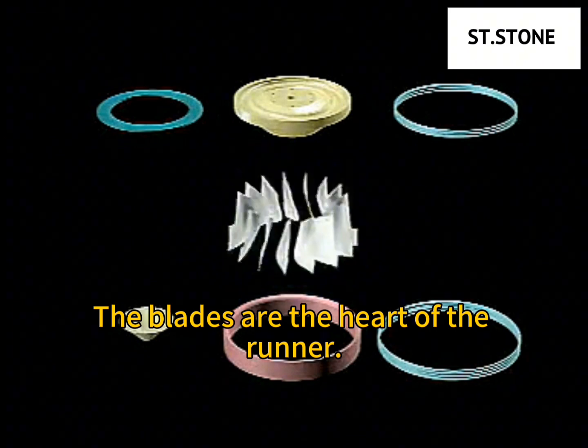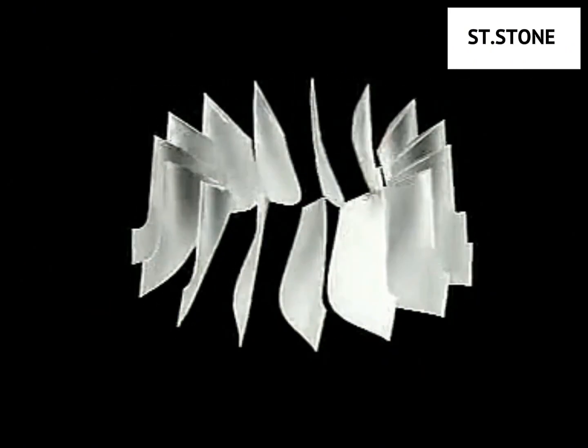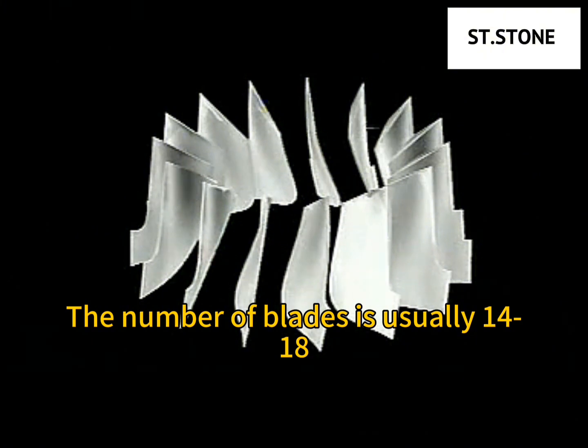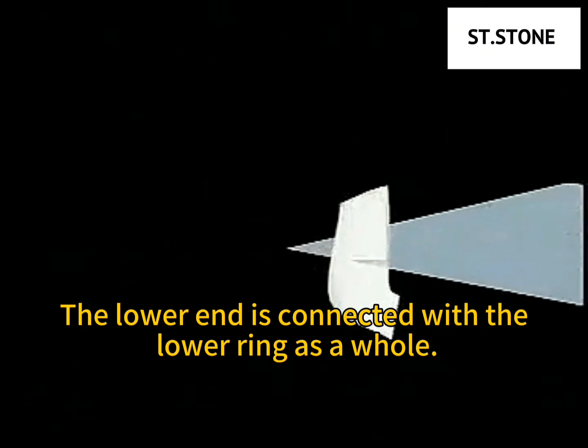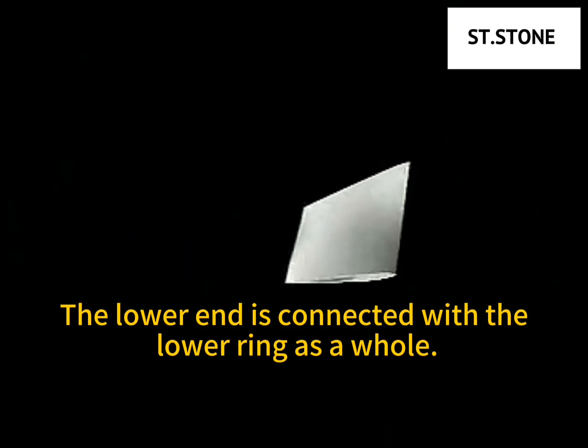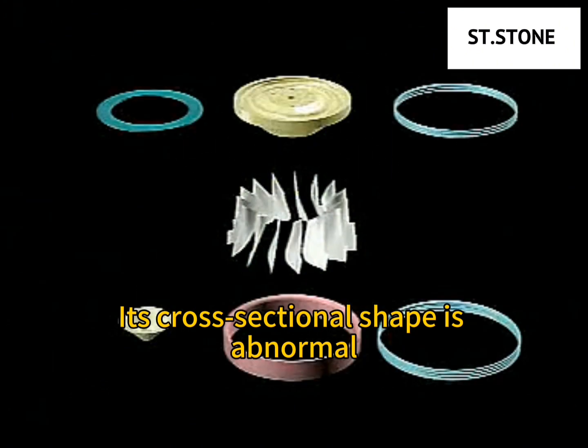The blades are the heart of the runner. They play a decisive role in how much energy is converted. The number of blades is usually 14 to 18. The upper end of the blade is connected to the upper crown. The lower end is connected with the lower ring as a whole. The blades are twisted. Its cross-sectional shape is irregular.